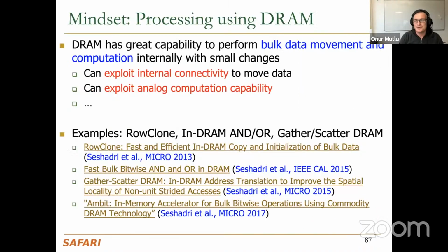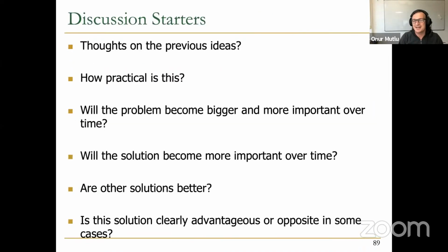Basically, if you do the slow copy, you don't reduce the speed, right? It's on par with what we do today with the intersubarray. So you don't lose anything, let's say, but you don't gain as much. Let me correct that. You gain in terms of energy, but again, as you said, it's not that much, unless you employ some of the later ideas, right? Like LISA.